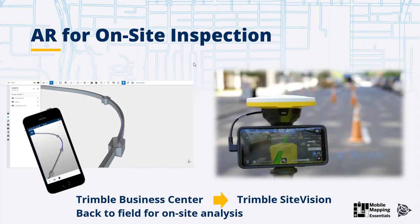The IMU we have is a kind of entry level, if you like, an AP15, which includes the GNSS antenna plus a MEMS IMU. This said, whenever you are in an urban canyon or a difficult GNSS environment facing significant outages, I would say the performance could be sub-meter, half a meter, maybe something like that. It really depends on the GNSS coverage conditions.